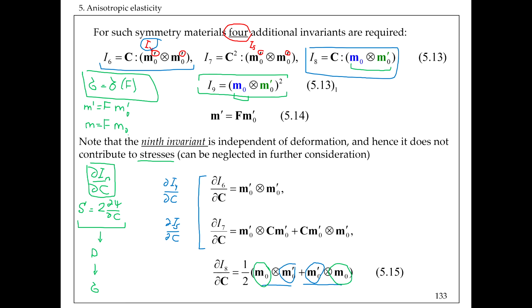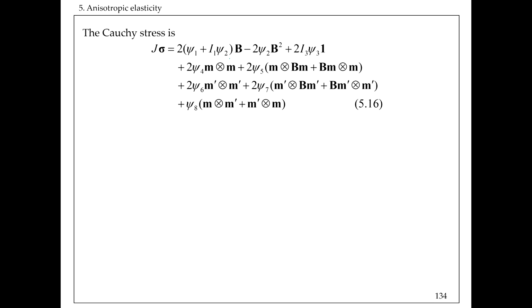And so for the Cauchy stress, now let's finally put it here. You can see once again that I have a few parts. The first part is coming from the incompressible material, so it's very familiar. It doesn't really change. Sorry, for isotropic material. So the first line, this isotropic elasticity, this didn't change. This is the isotropic part right here.